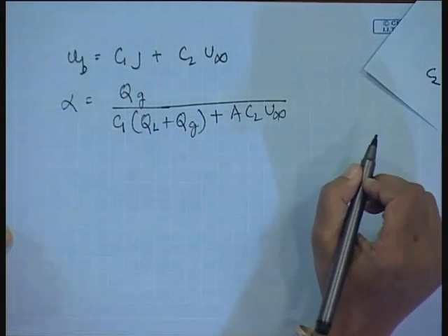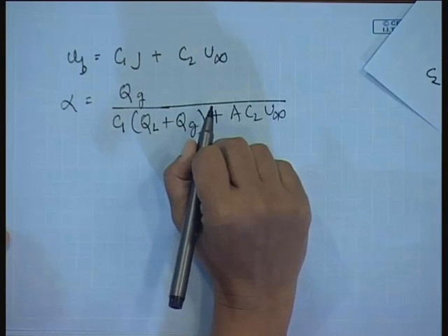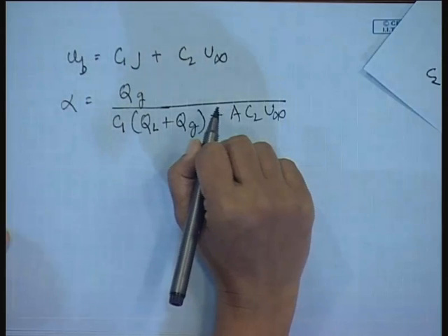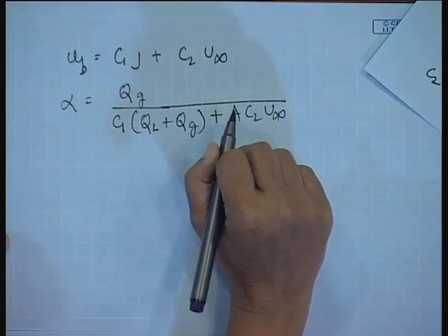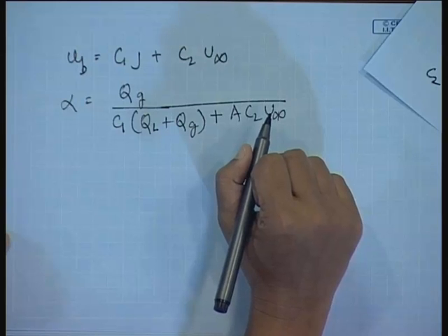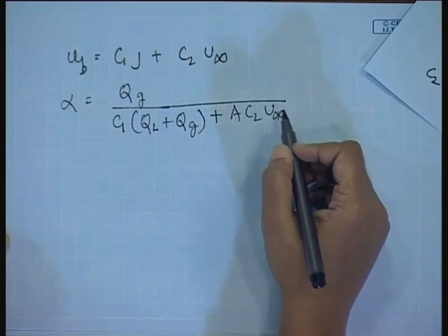When we account for the wake effect, or rather the measure of the change in relative velocity due to the approaching velocity profile, as well as the fact that the bubble rises not with respect to the average velocity, but with the weighted average velocity. So this is the final expression that we get.